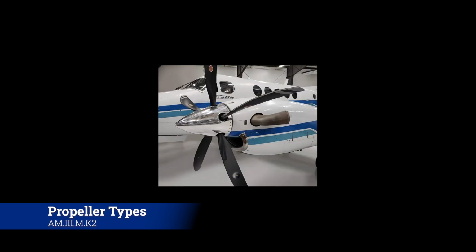Okay, so here's an example of a constant speed propeller on a King Air. If you had a fixed pitch propeller on this particular aircraft, it would be highly inefficient, and you would lose a ton of performance. You'd also not be able to get into half the airstrips because you would, for one, have to get the engine up to speed and then get the aircraft up to speed for the propeller to produce enough power, enough lift or thrust, to get off the ground. And then you would be dragging in the air at certain airspeeds.